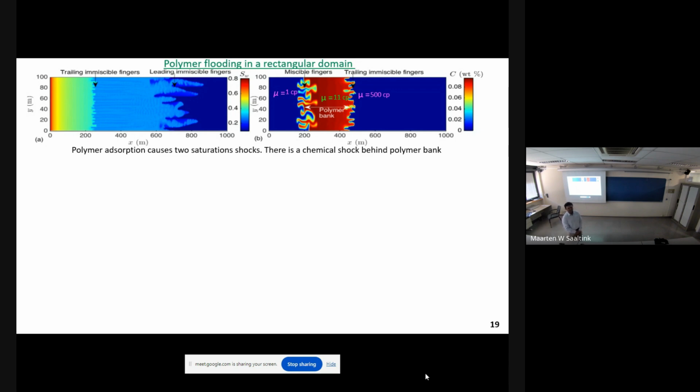But there are two critical points here. One is the onset time, when does the instability start to grow, and the other one is the wavelength of instability. It's possible to do this analytically by a normal mode method. People do the normal mode method. This is a bit complicated for radial, but anyway, slightly simplified. You linearize, of course. Sometimes it is complicated. This is viscous instability, caused by viscosity.